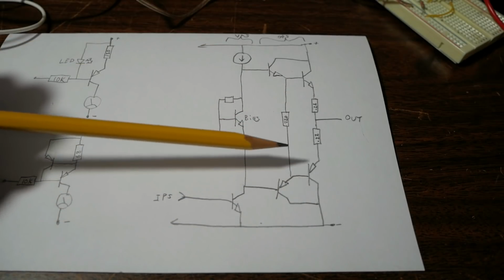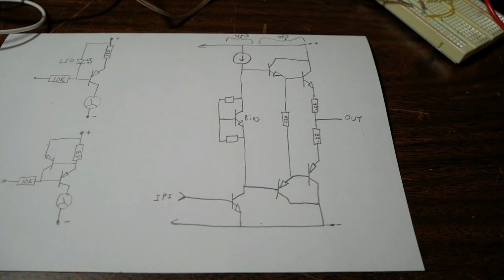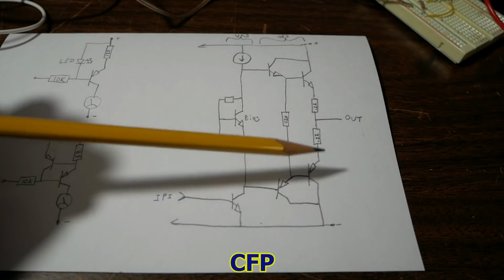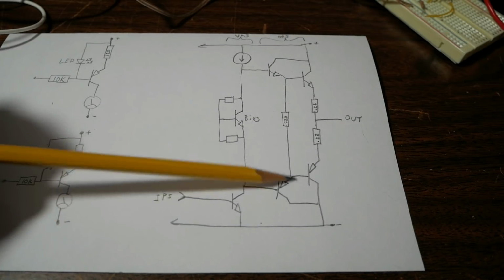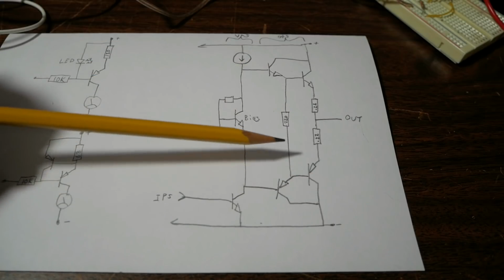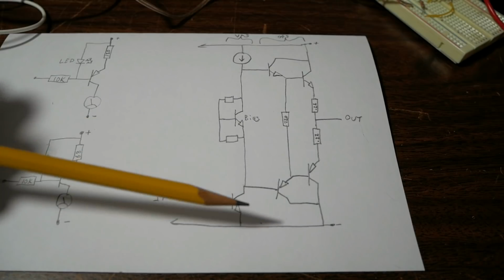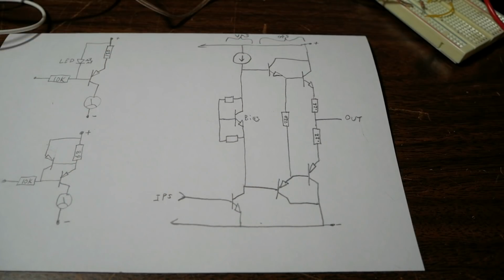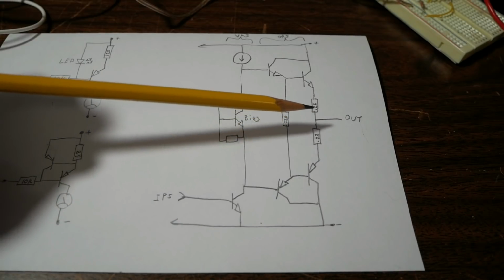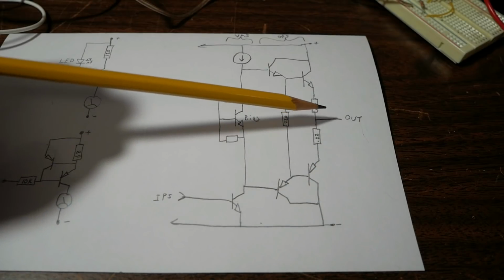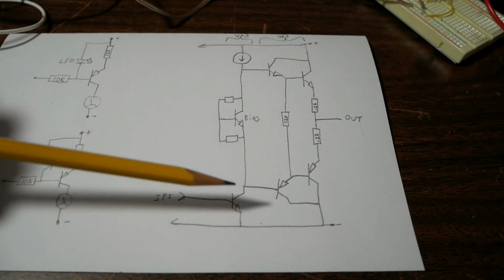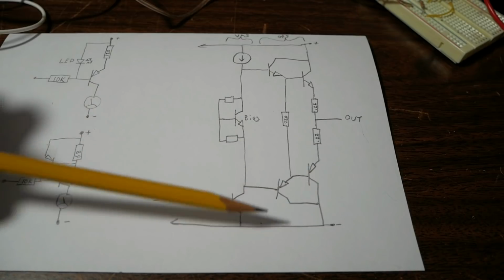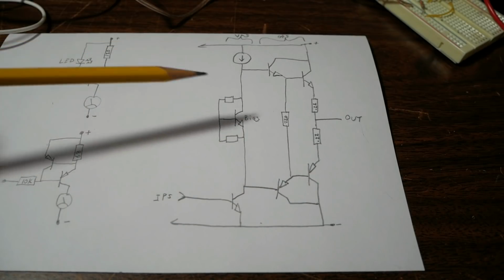A vast majority of amplifiers these days have emitter-follower type or complementary feedback type designs. And in fact, most engineers and amp designers frown upon output stages with voltage gain. So these stages are designed so they only provide current, no voltage gain. So it's up to the VAS stage to make that voltage swing as large as it can possibly be before it gets into the output stage, because you need a large voltage swing to drive your load to get the most output power. I should mention at this point that this is a very minimalist drawn diagram here just for the purposes of explanation. I left out some of the components and it might even change.